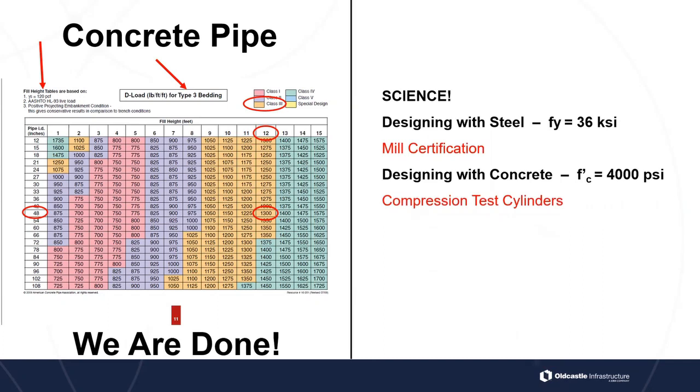I can take a test cylinder and do a 7-day or a 14-day or a 28-day break in my quality control lab, and I can determine that that concrete either meets or exceeds the 4,000 PSI compressive strength. Boom, done. I can test it.